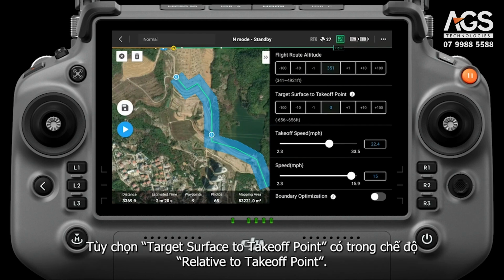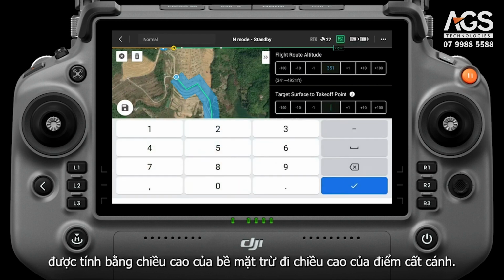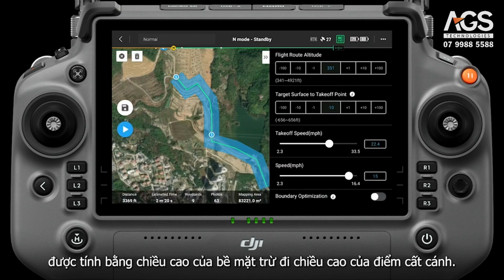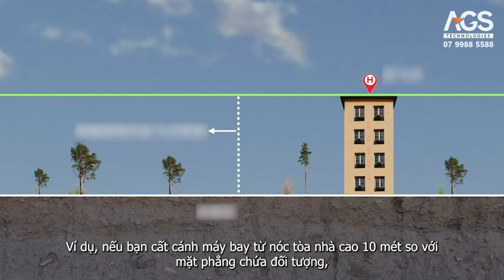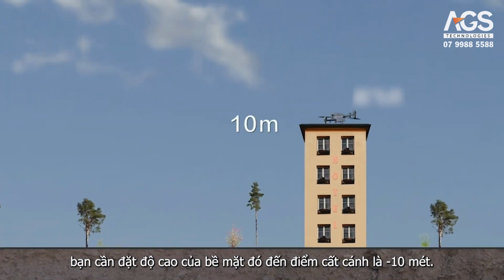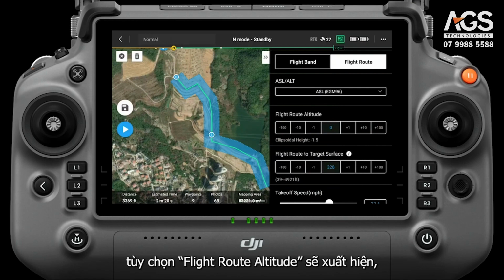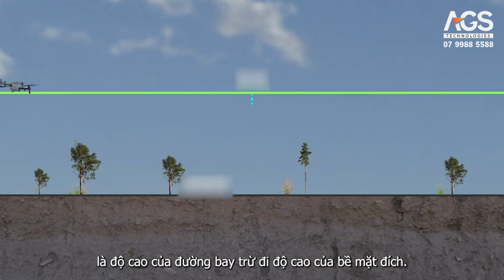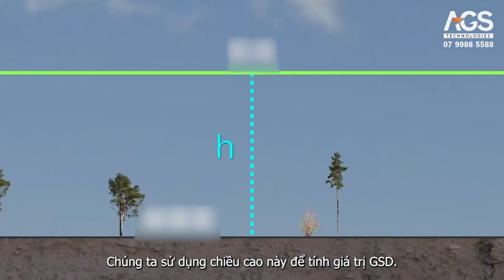Target surface to takeoff point appears in relative to takeoff point mode. The height of the target surface to takeoff point is equal to the height of the target surface minus the height of the takeoff point. For example, if the aircraft takes off from the roof of a building 10 meters high above the target surface, you need to set the height of the target surface to takeoff point to minus 10 meters. When ASL is selected, the flight route altitude option appears, which is the height of the flight route minus the height of the target surface. We use this height to calculate the GSD value.